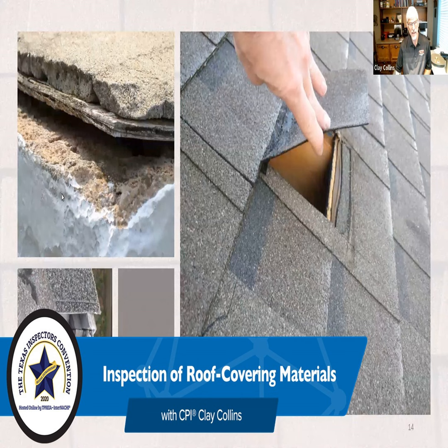The 3-tab shingle is generally considered to have a 15 to 20-year life. You'll look on the package of the 3-tab shingle, and the manufacturer might say it's 15 years, and they might say it's 20 years. In my explanation of the type of cover to the client, I will say that it might be sold as 15 or 20, and the average life expectancy is generally between 15 and 20, but closer to the 15-year, assuming no acts of God, including hurricanes, tornadoes, tree limbs, and satellite antennas. And then there's always the case of the homeowner that gets up there and does something stupid.